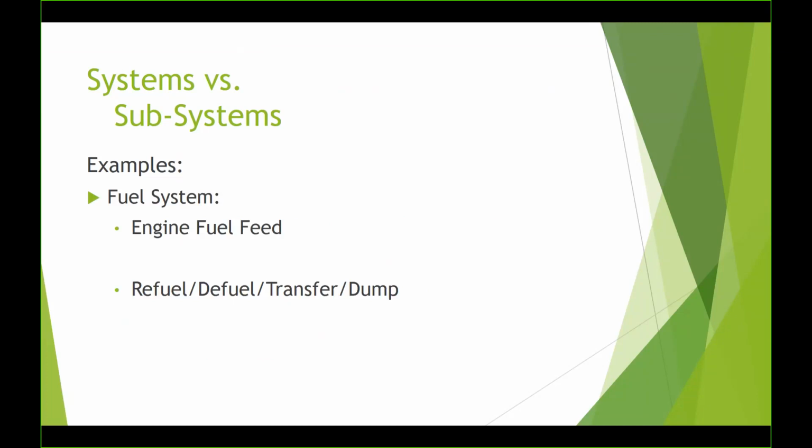For larger aircraft, there's a requirement that airplanes have to be able to get down to their maximum landing weight within, depending on the airplane, typically somewhere within 90 minutes or so. And so if they can't burn the fuel down fast enough, they have to be able to dump fuel. The 727 we have out on the ramp has a fuel dump system on it. If you push the breakers in, flip the right sets of valves, and turn on the right pumps, it will dump fuel onto the ground. We have those breakers collared for a reason. Okay? You've got to kind of know what you're doing to get it to happen, but it can, in theory, dump fuel all over the ground if you're not careful.